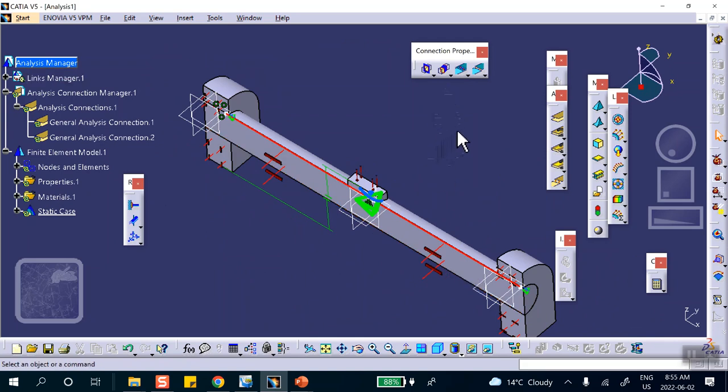What kind of a connection is this? If you bought this shaft and brought it home and stuck it into there, what would the nature of the connection be? This is saying they're friends and enemies and relatives and things like that. It doesn't say how. Connection simply means there is a relationship between this surface and that surface. It doesn't say how. If the problem statement says that end I put in there is fully bonded, fully glued, whatever, then it's going to be faster. Otherwise, it's a contact connection.